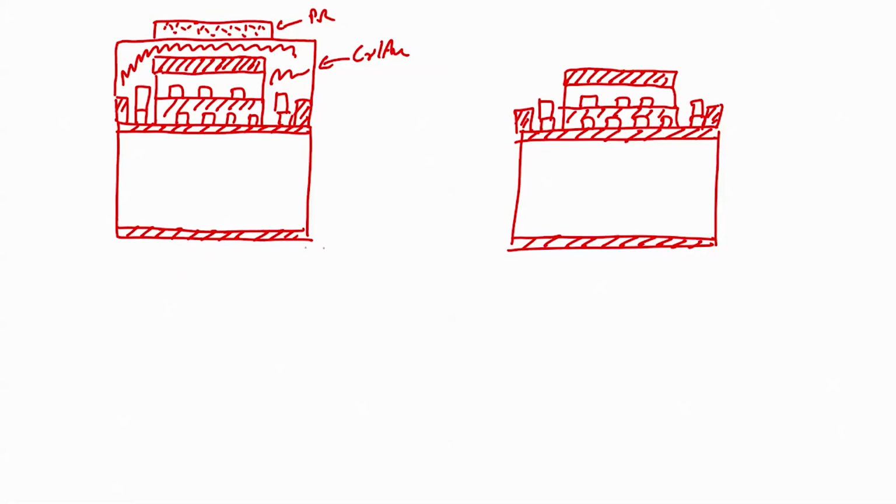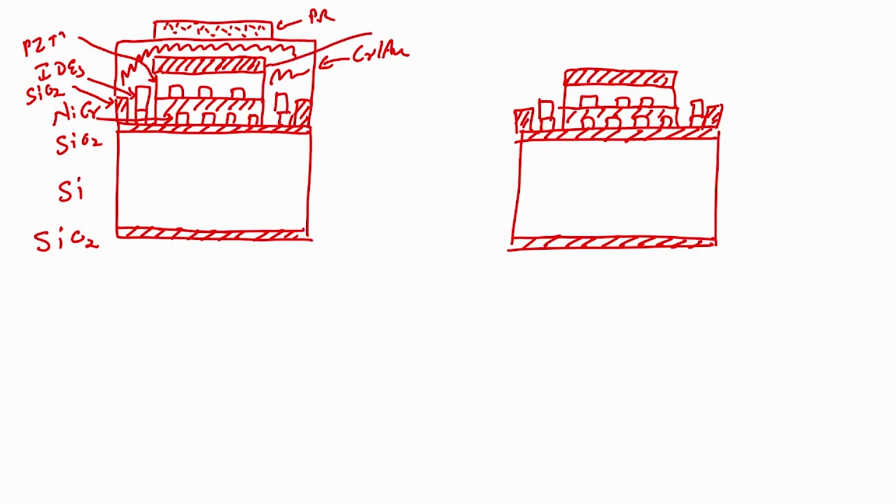And if I dip this wafer, so if I write down SiO2, silicon, SiO2, micro heater is nichrome, then SiO2, then interdigitated electrodes, then piezoresistive material, then SiO2, on which there is a chrome gold, on which there is photoresist.